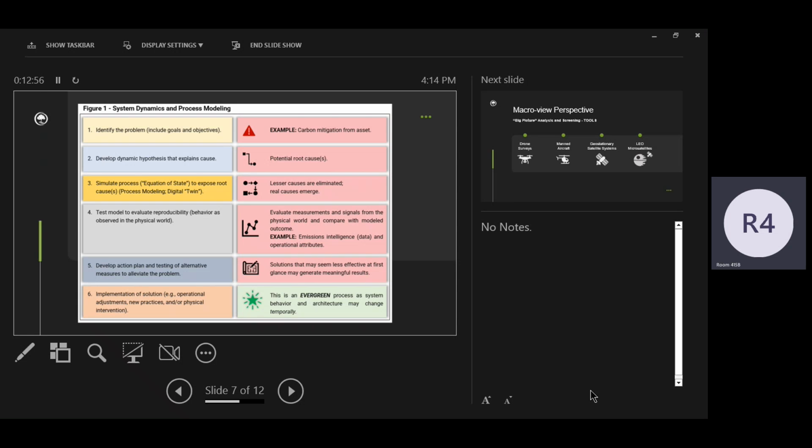So you did not have like-in-kind union on the pneumatic devices. They found out that their contractor had a bucket of Parker fittings and Swagelok nuts and they were just putting this stuff together. We were able to resolve that by simply using like-in-kind materials, building the facilities as they're supposed to be built, and then voila, that leak is gone. And then we can track that, we can learn from that,